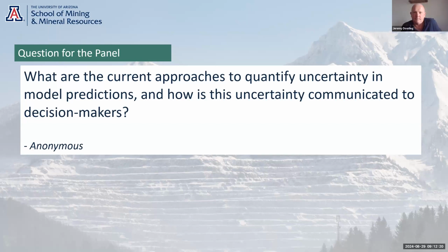Yeah. Just to build a bit on the first thing you said, Jim, I think the bottom line for slope stability is head or pressure. So I've always liked your approach of varying the head in the numerical model, which is the bottom line of what you're trying to predict, rather than varying permeability or storage.